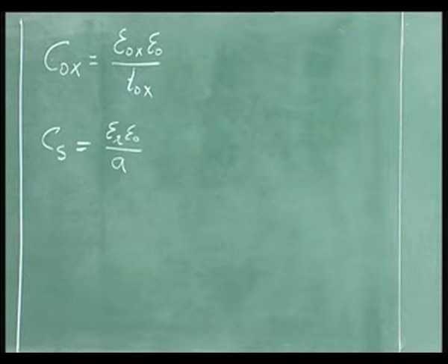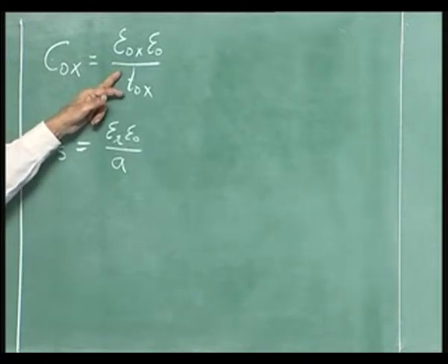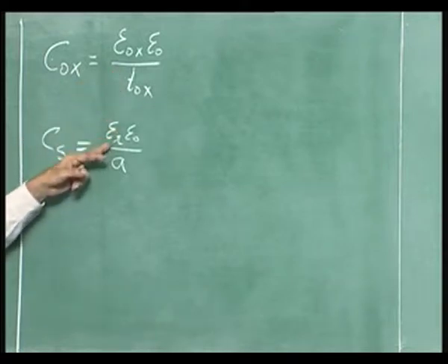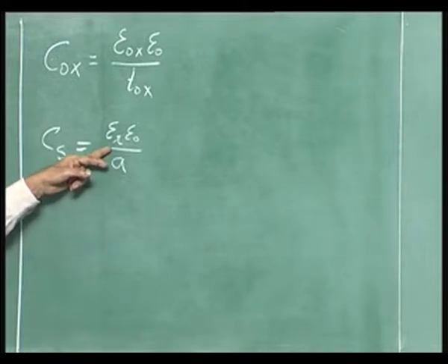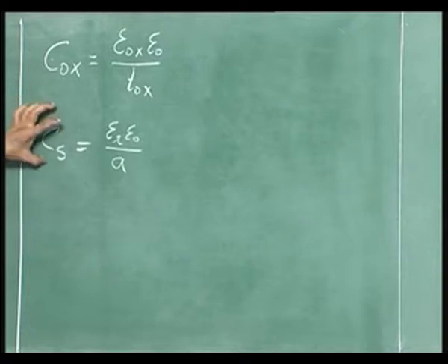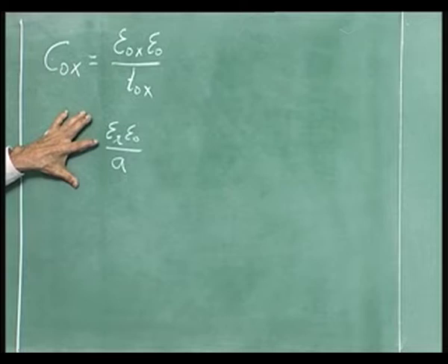Okay. Now, notice here between these two, for silicon this is close to 4, people talk of 3.94 in that range, 4, and this is for gallium arsenide 12.8, silicon it is 12. So, whether you talk of silicon MESFET or JFET or silicon MOSFET, this term is larger than that, at least about 4 times larger.